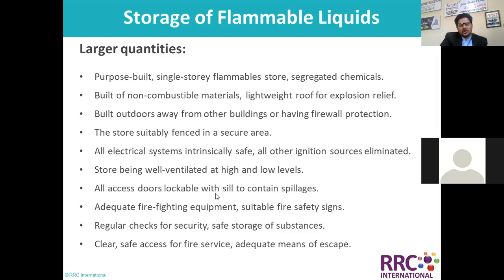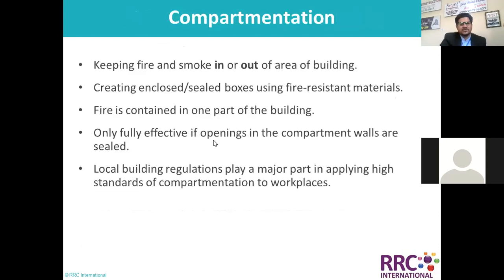All access doors should be lockable. Adequate firefighting equipment must be there with safety signs. Regular checks for security, safe storage of substances, and clear safe access. So these are the same general principles or rules for storage of flammable liquids, especially for larger quantities.